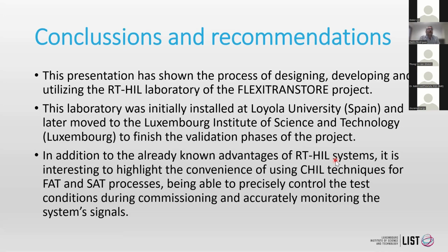We were able to use all this setup for generating the signals for testing the equipment in the factory, so we were able to design all the factory acceptance tests. Later on, the batteries were shipped to the final location, to the site, and we also ran the site acceptance tests using the same operating conditions as in the factory. Those were excellent operating conditions.